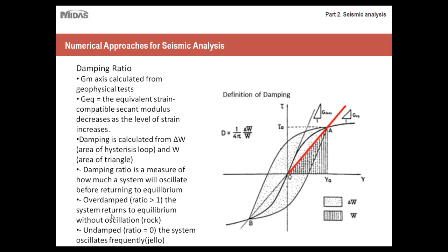So that's the main difference to take into account: the higher your damping ratio is, the more resilient or the more stiff your soil will behave when seismic loading is applied to it. Whereas if it's closer to 0, the more it'll give way to seismic oscillations even after the earthquake is gone. And once again, I won't go into too much detail about the loop itself, but just keep in mind that your damping ratio is directly related to a model such as this.